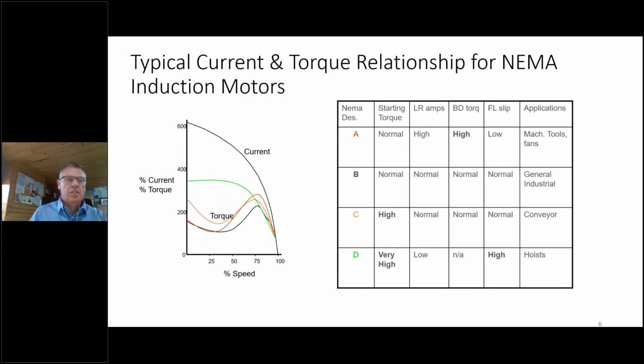When the AC kicks in, you may notice that the lights flicker, and that's because of this inrush current. So 600% inrush, and then you're moving to the 100% current, the full load current at normal operating conditions.